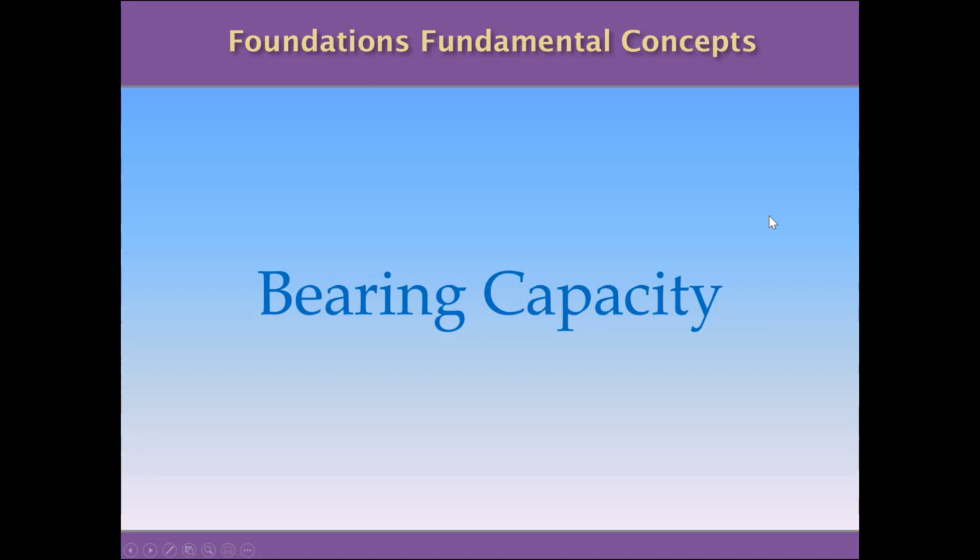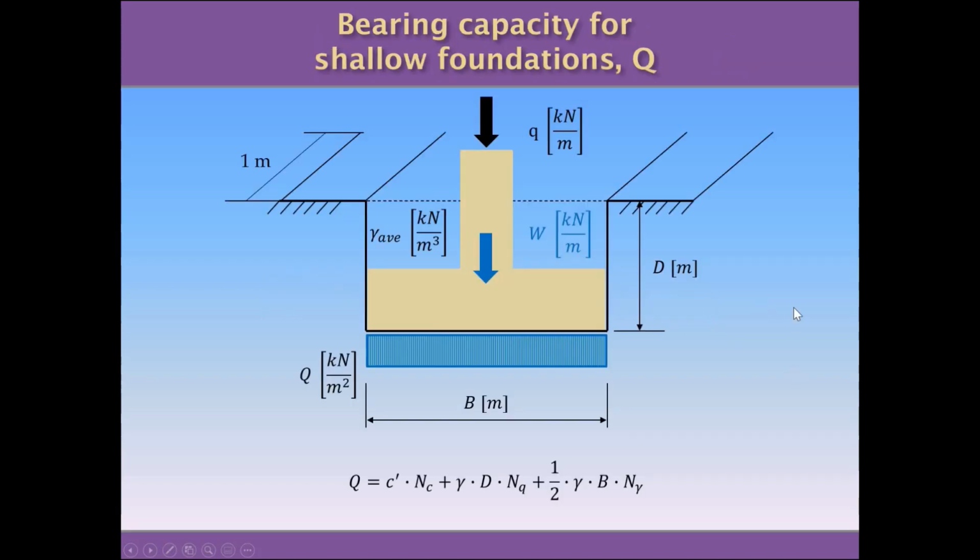So now we have discussed the three main concepts around foundations, which are the effective stress and the failure criteria, and we have discussed as well the types of foundation. It's time to discuss the bearing capacity. The bearing capacity is the capacity of the soil to take loads. So we need to establish in some way how much capacity we have for every case, in order to compare with the loads that are coming from the building and be sure that we have enough bearing capacity to support them.